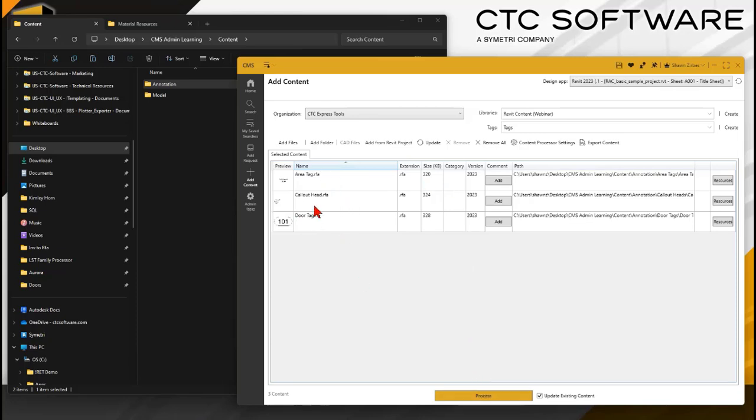And then it moves on to the next family, and it does the same thing. So with Revit family content, RFA content, all that matters is the version of the file, and that you have available either that version or a newer version of Revit available for it to open and scan that content in that version, okay?